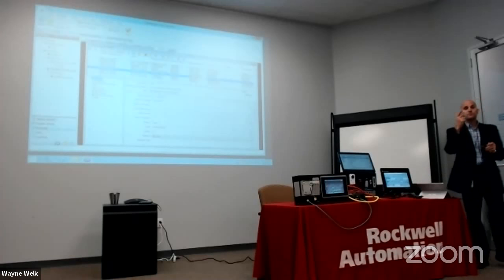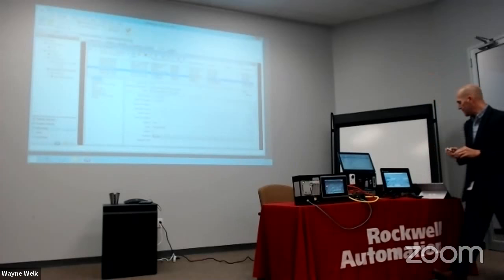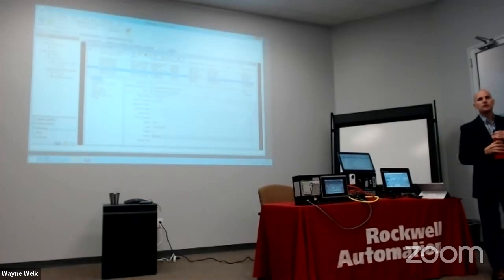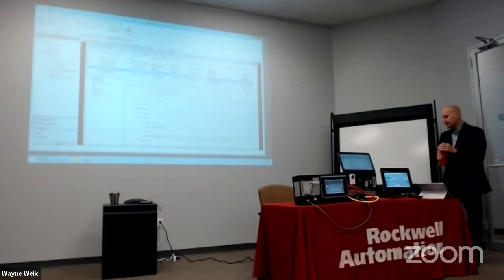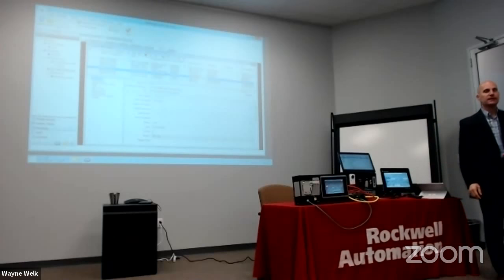Yes. So we're currently using ThinManager. Yes, sir. And we have some projects coming up where we're putting IP utility cameras subsea. And in the past at Oceaneering, we just throw a separate monitor in the control van. We're running RTSP, and we've heard we can do this, that we can put it right onto the FactoryTalk SE HMI. Correct. I'm going to make that a question and a statement. Yes, you can do that, and it's currently being done.